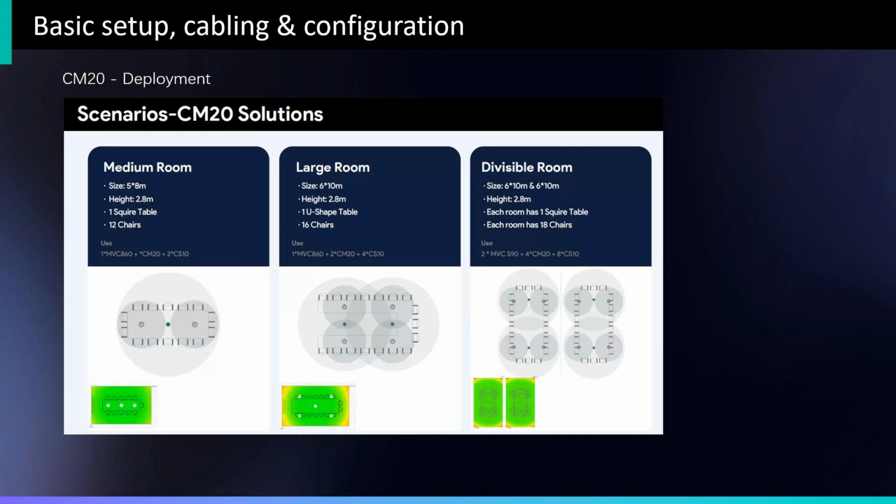So from that perspective, we can calculate, all coming down again to the room audio. If we have a room with a lot of echo, a lot of reverb, a lot of glass and reflective surfaces, we have to go down the path with more microphones, which limits the size of the room we can deploy with that gear.